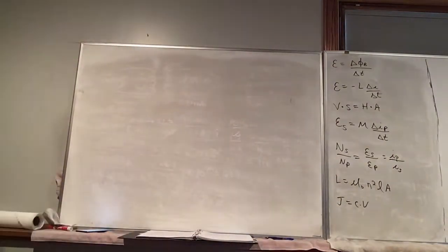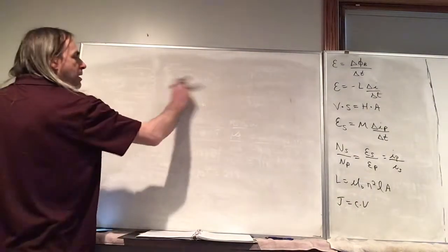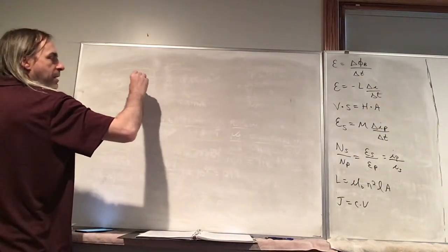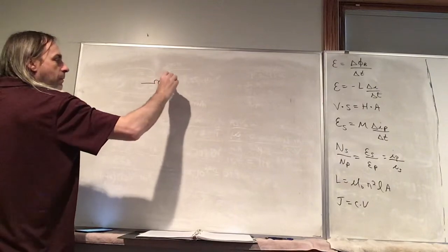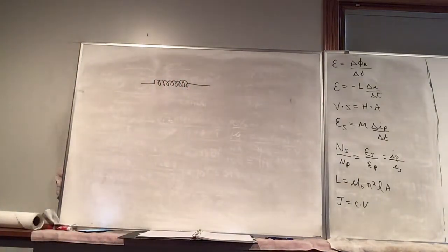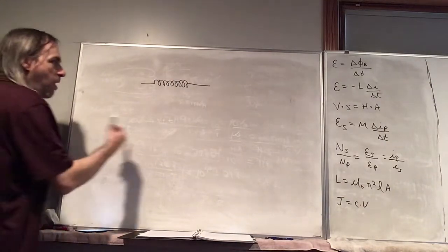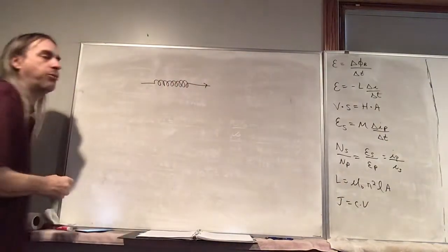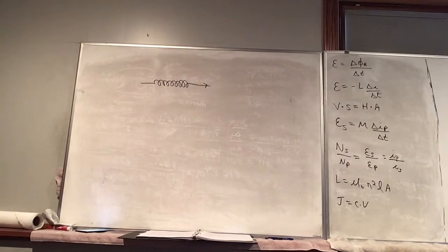Well, it's in the notes, but the energy, like if we start out with the solenoid and there's no current, let's say we apply a current, so we have to apply a voltage, and then we can turn on a current, but the solenoid is going to fight us, because when we establish a current, there's going to be a back EMF.